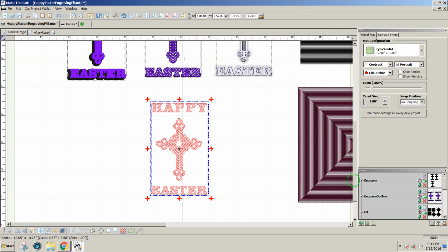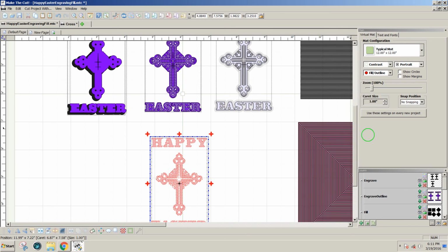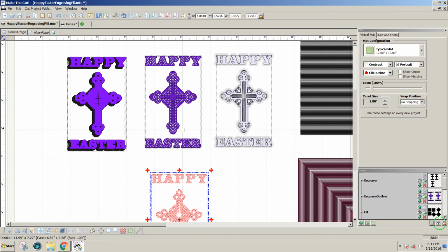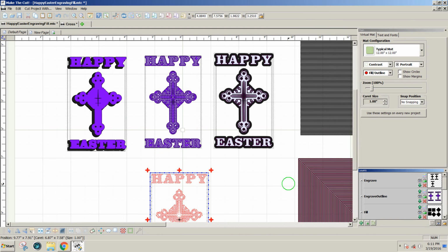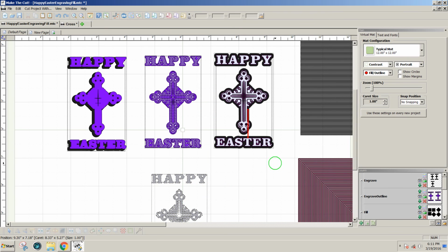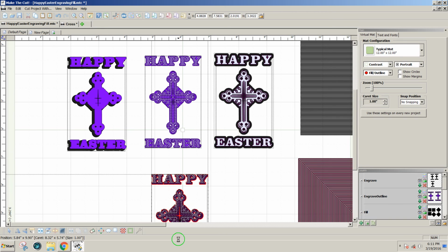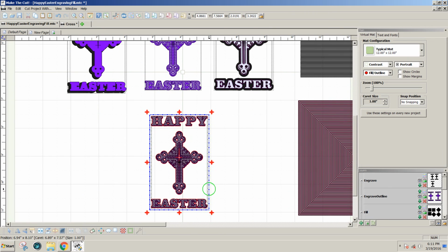Now once I have this shape, I'll want to grab the shadow so I can show all layers, and I can grab not the cutting line, but I'll undo that, and I just want to select it and hold Control Shift and drag so that I select both the outline and the design and type S to stack them.